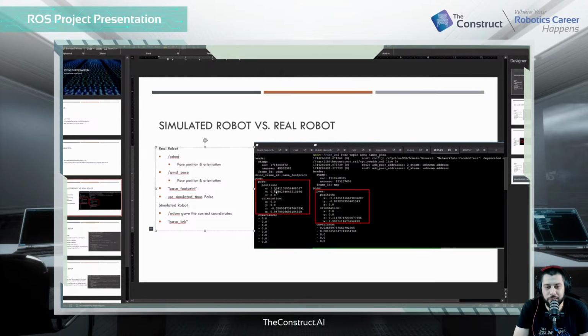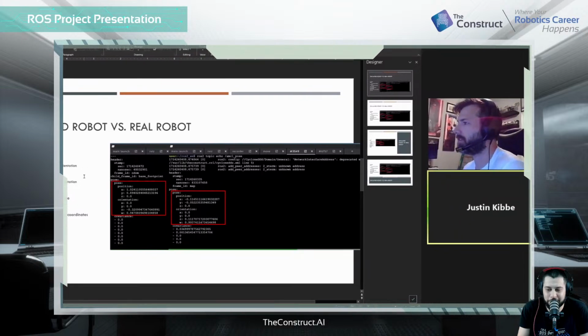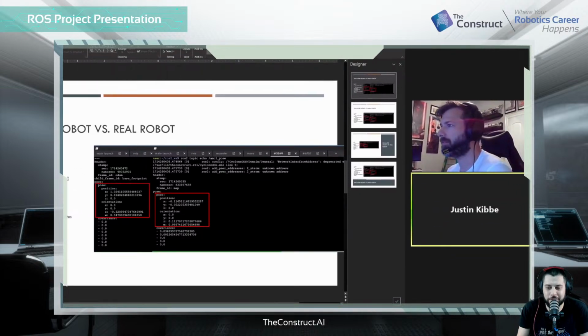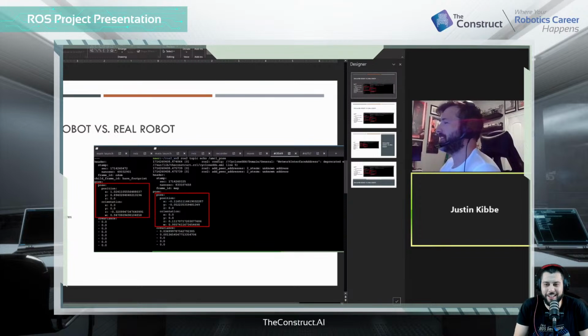So I wrote out, when I was going to save my points, code to access the odometer, go into that pose and hold the points. And it did work. It worked in the simulation. And then when I got into the real robot, I was getting so frustrated. I would save a point and then submit that point for navigation. It would go somewhere completely different than I wanted. It took me a long time to figure this out.